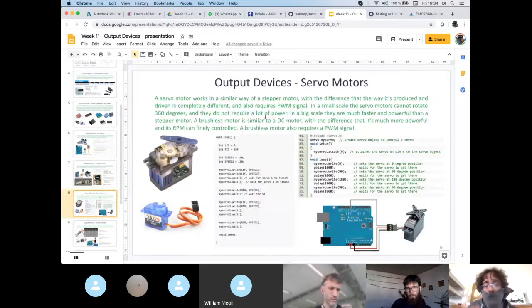So here there is a simple example, actually 2 examples, about the servo motors. Here we just use the small ones that can be driven directly from the microcontroller. In this case, these often have 3 connections. So you need VCC, ground, and the signal itself. Usually these ones work at 5 volts or 6 volts, so they can be run directly, and less than 40 milliamps.